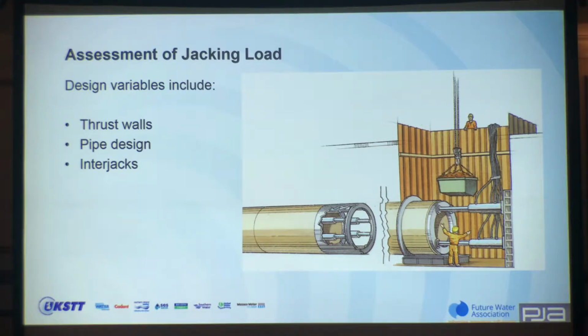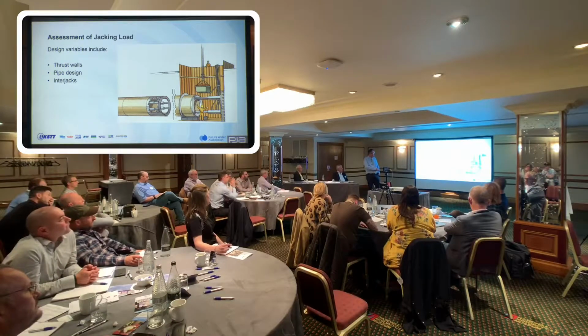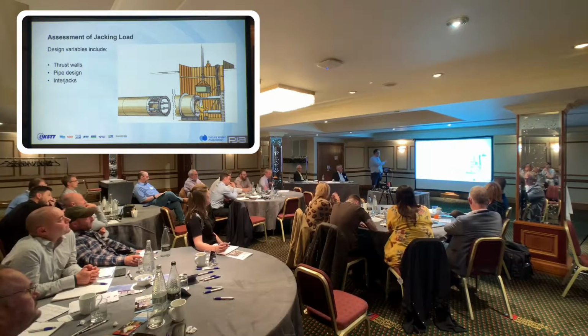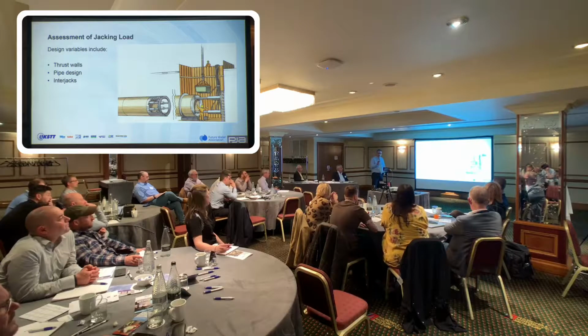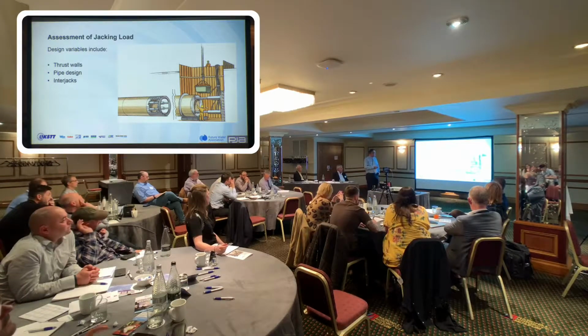Interjacks, we mentioned those a couple of times. Again, the one on that little schematic is showing the back of the pit and the main jacks, and then there's a brake and the interjack. So when you're thinking about the jacking loads in terms of designing the back wall, you need to understand what you're trying to limit the load to, and indeed how many interjacks you think you're going to use along the line.